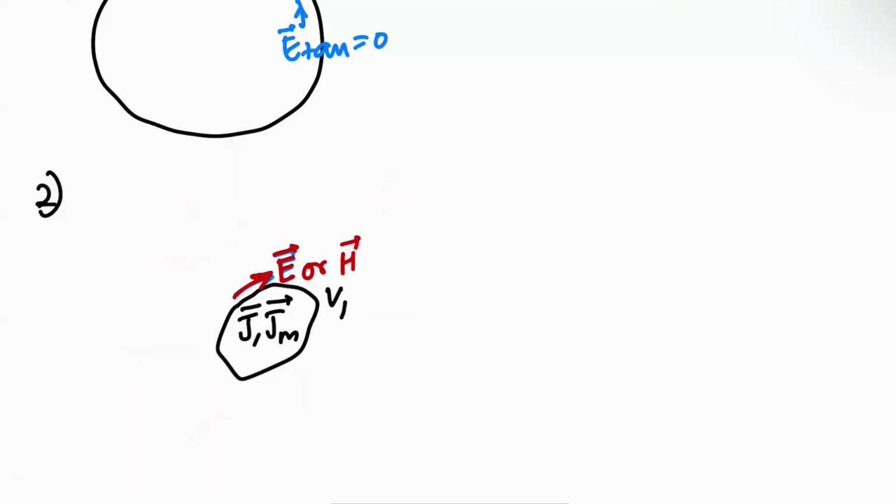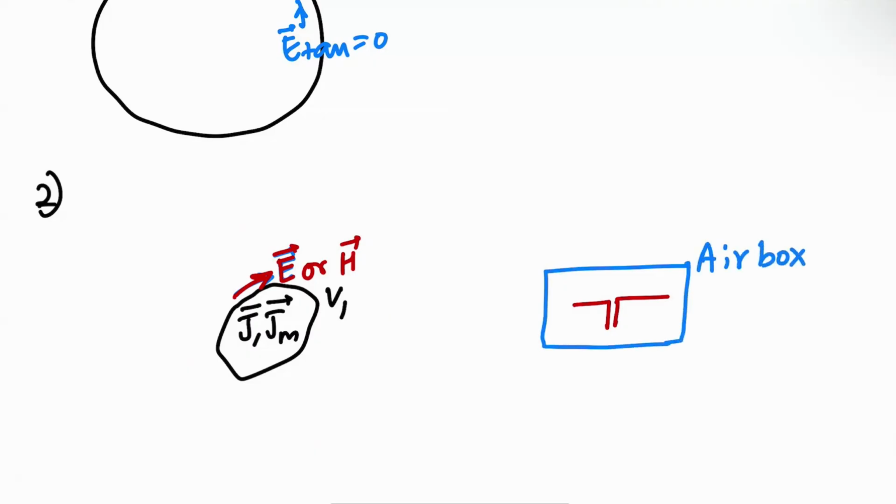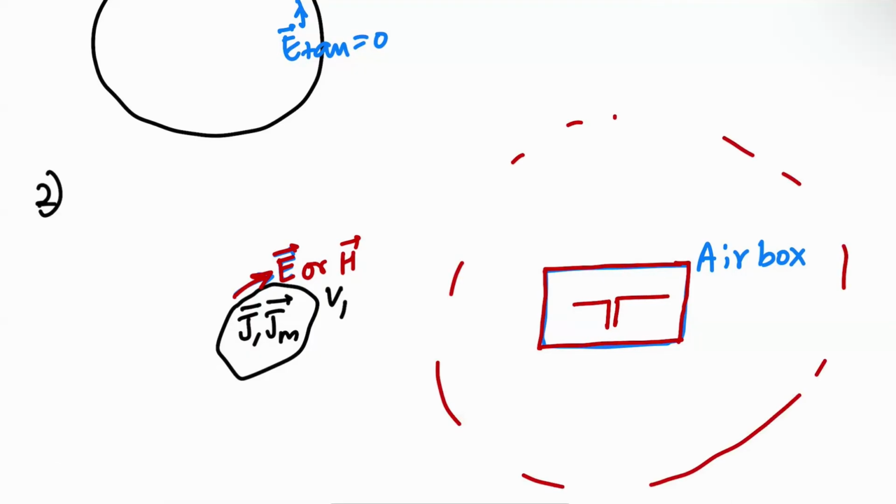And this is also something that HFSS uses. You have your antenna, and there is a bounding box that you apply, which we'll see. This is your air box. HFSS essentially calculates what the tangential components of the field are on this air box, and from that, you can uniquely calculate what the far field is everywhere. So again, uniqueness plays a big role there.